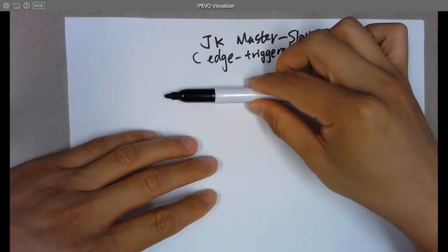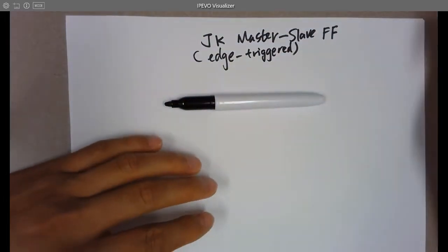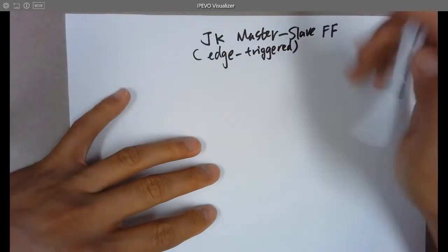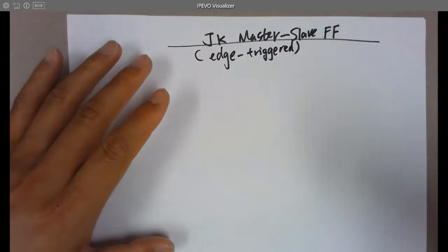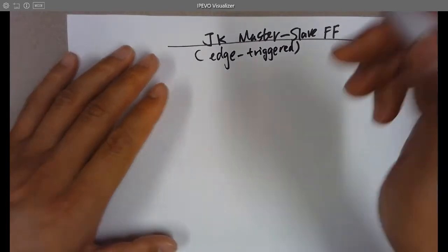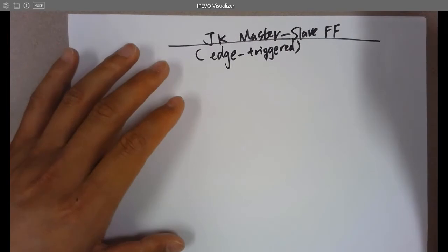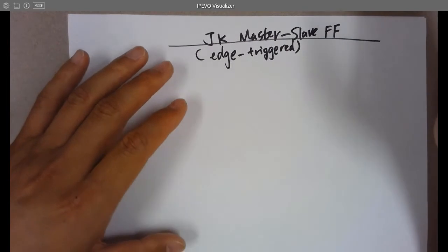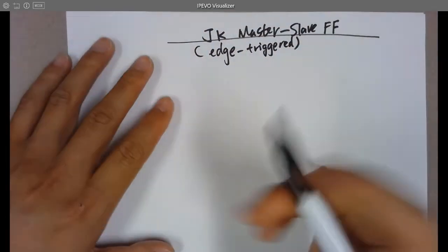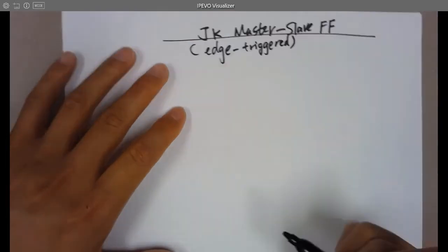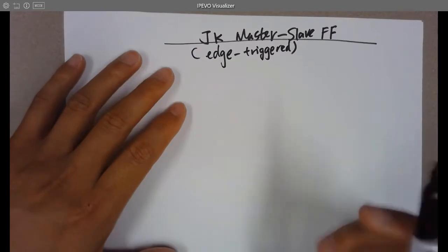Whenever the clock is on, all the signals will be passed to the latch, which is not really practical because you don't want that to happen when you have a clock. You just want this one to go there as an edge, then just stay there, don't change at all. You don't want anything to be changed other than at the edge. This one has that benefit: it only allows data to be passed to the latch at the edge.